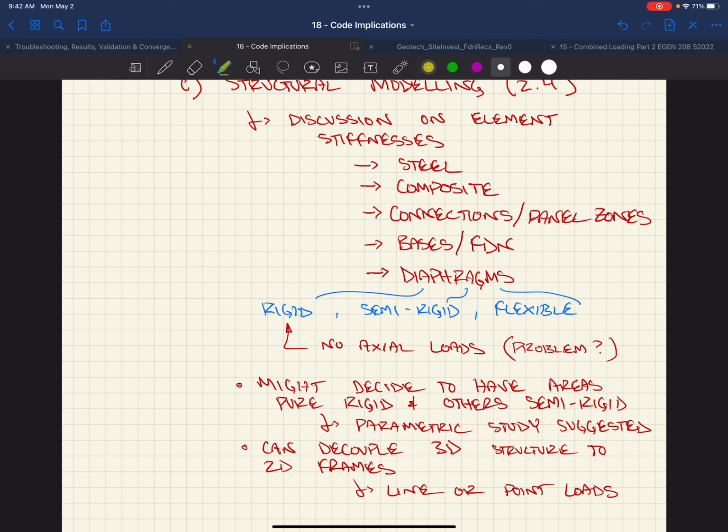It's not going to act as a beam. It's not going to crack or rotate in the plane of the diaphragm. Any bad things associated with that? Still think so. You're talking about preventing in-plane movement or this complete stiffness? Yeah, so axial forces will not develop in horizontal members connected to the diaphragm. Well, we have drags, chords, and collectors that all need to be designed for axial forces,